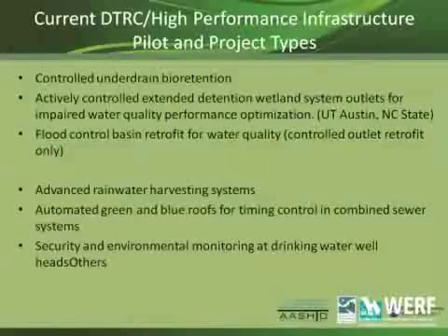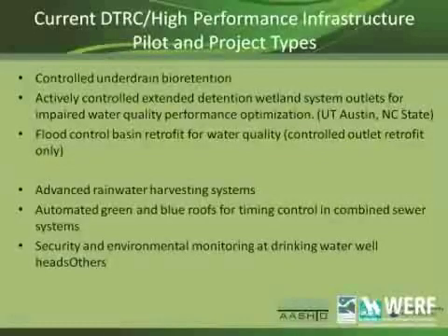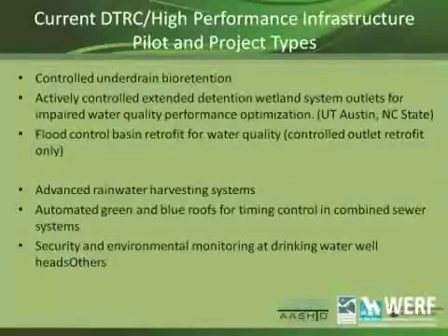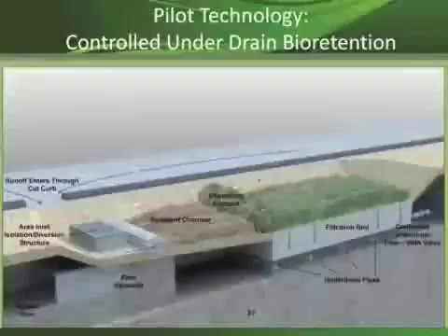You could change the way an extended detention system, whether it was a wetland or, say, a retrofit of a flood control basin, you could change the way that operates, maybe take advantage of the space in the flood control basin, but if a flood event is coming, you drain it and get it ready. And it's also looking at some other BMPs down below, but I won't go into those.